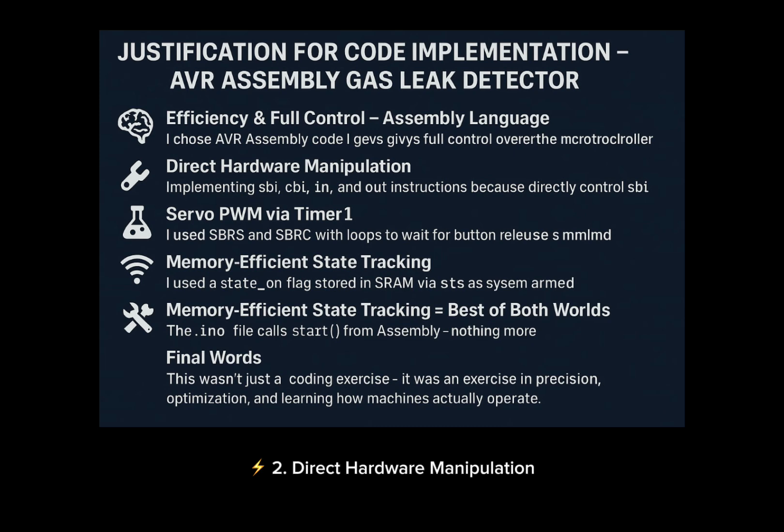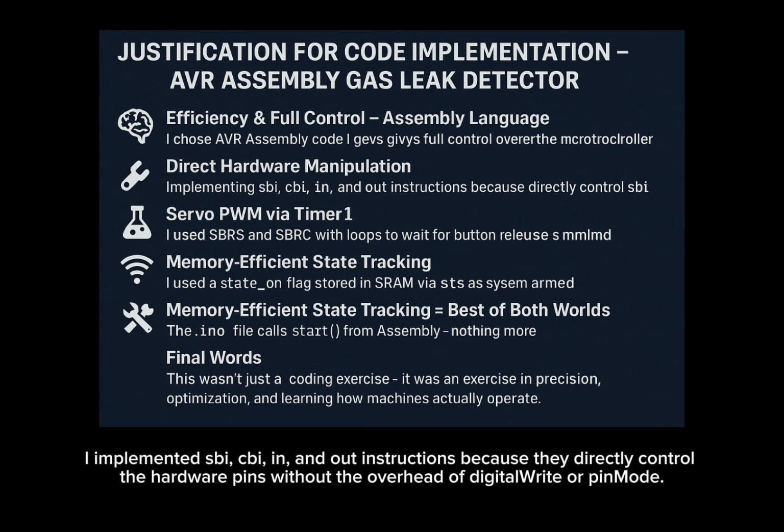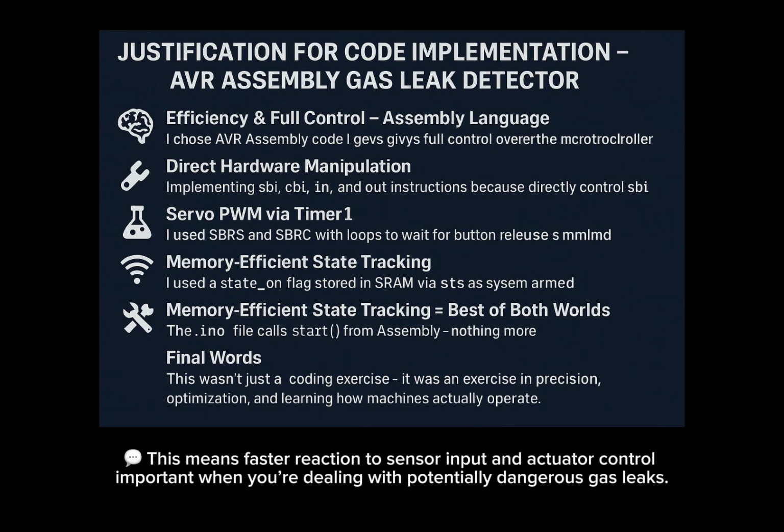2. Direct hardware manipulation. I implemented SBI, CBI, IN and OUT instructions because they directly control the hardware pins without the overhead of digitalWrite or pinMode. This means faster reaction to sensor input and actuator control, important when you're dealing with potentially dangerous gas leaks.